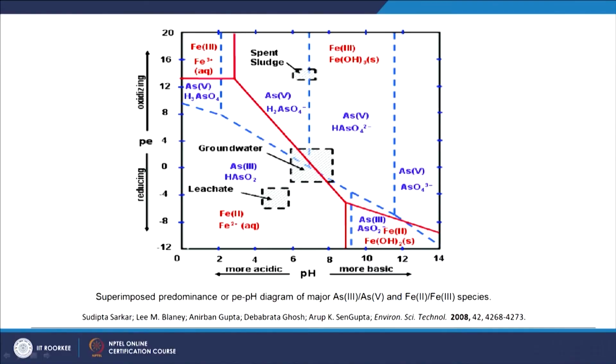As you see here, in most of the pH range, if it is the reduced form, as in As(III), HAsO2 would be neutral, it has no charge. So will that be suitable for removal by ion exchange? No. But if I consider the more oxidized form, arsenic in oxidation state 5, I see that even from pH 2.2 or so, it has a charge, and at neutral pH it is either HAsO4- or HAsO4 2-. So the compound has a charge on it. If it is charged at neutral pH, it is obviously amenable to removal by the ion exchange process, and I think this is one example that we have looked at, but this gives us an understanding of it.